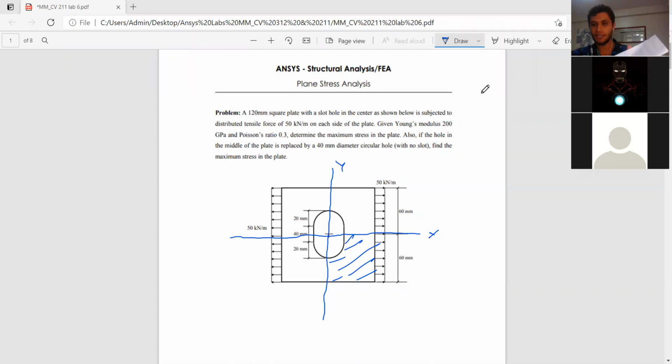So what we have essentially is a full plate and we're applying a load this side and this side. I'm making it tense, tensile stress in the middle. What I'm saying is we could fold it in half and simulate this side pulling, and then mirror it about the y-axis so it looks like the same thing. Or we could fold it in half this way and pull it this way and mirror it about the x-axis.